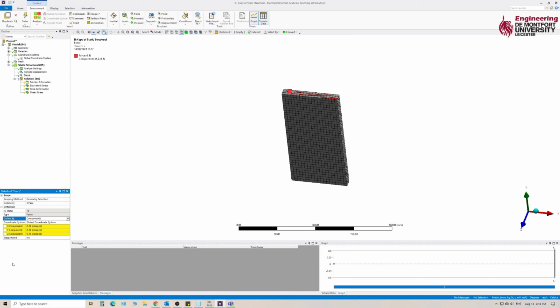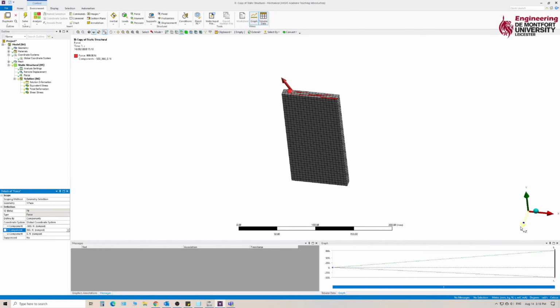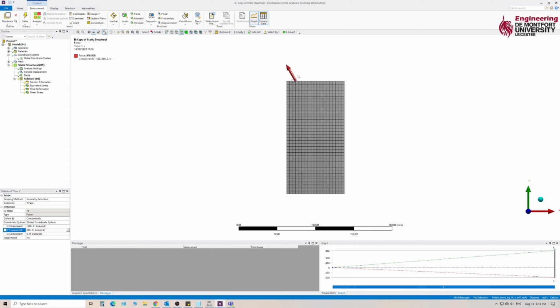So in the x direction, that would result in 500. However, we need to have a look at the direction of the coordinate system. So plus is that direction. I actually want it to go minus. So this needs to be minus 500. And then y will be 866. Okay, and so we can see we've now got a force, and that will be clocked at 30 degrees.